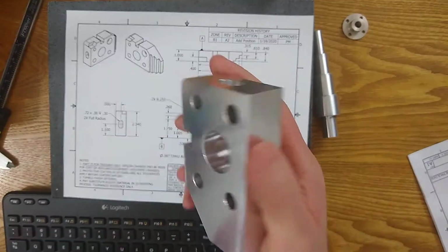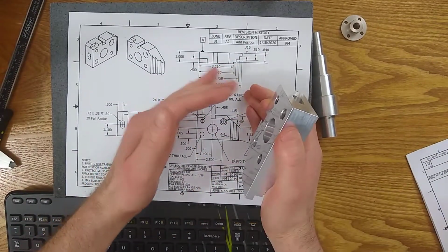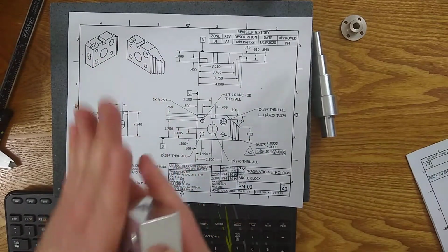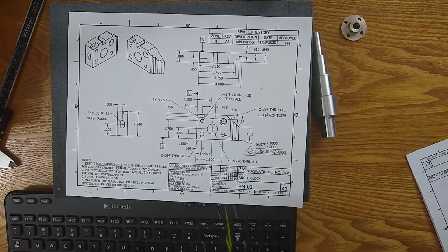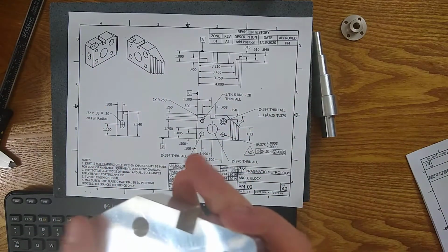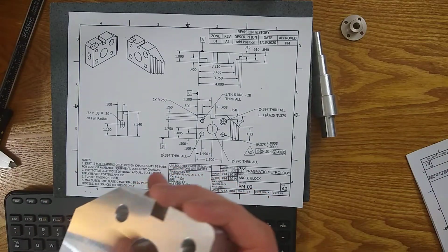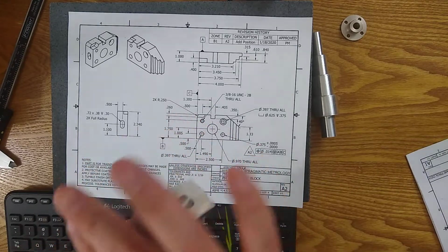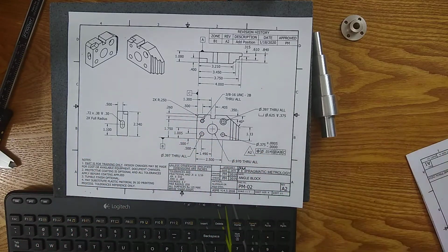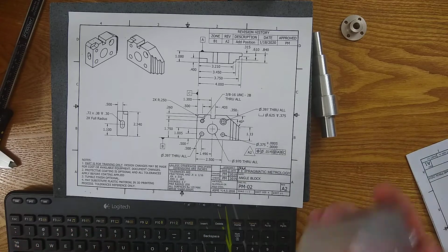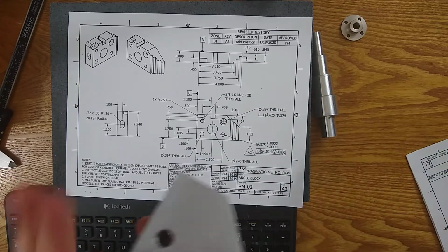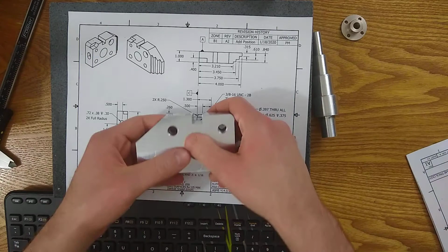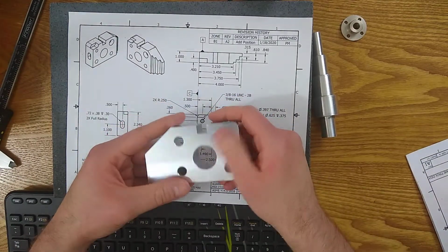At least from a design perspective, these are your perfect 0, 0, 0 intersects. Now, the manufacturing process may not make them perfect. I talked about an example in the last video where sometimes the datums are not made perfect, which affects every feature off of the datum, which is a problem. You generally like your datums to be in good condition, but that doesn't always happen.